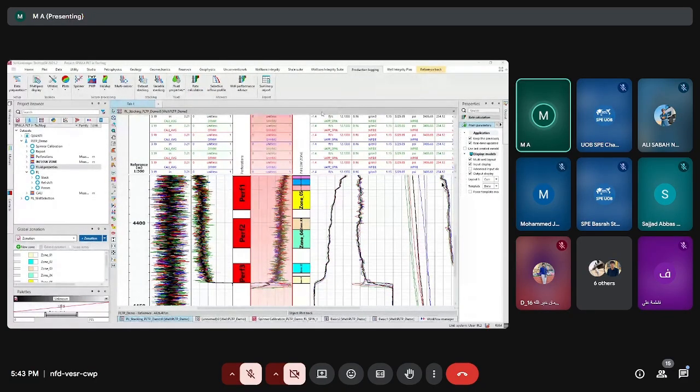For the rate calculation, I'm going to tell the software this is the temperature, my pressure, my caliper. If I go to my stock data here, I have used the caliper average. So I'm going to tell it this is my caliper, this is, for example, the density, this is my apparent velocity, the density, water holdup, and the gas holdup.